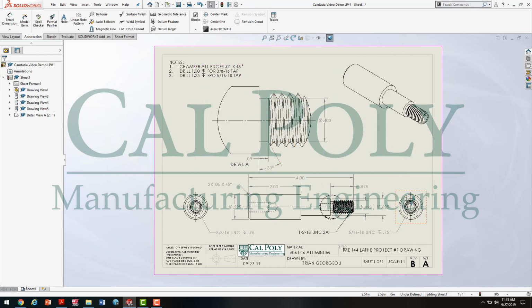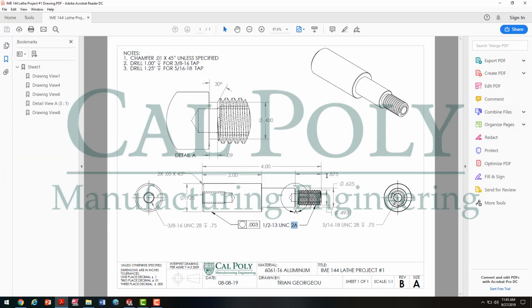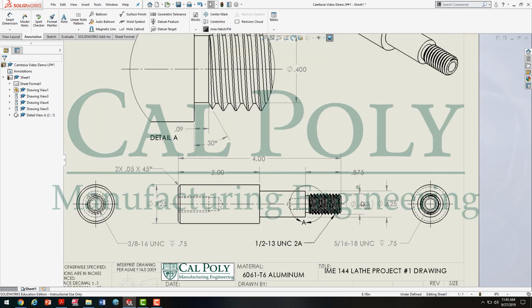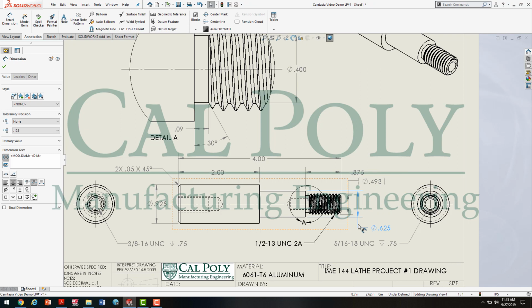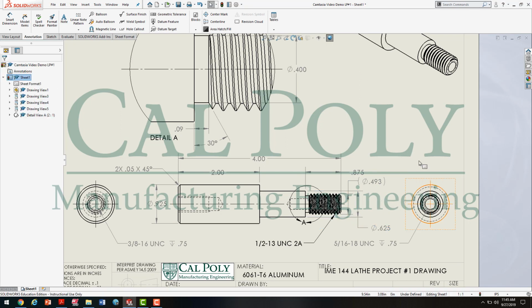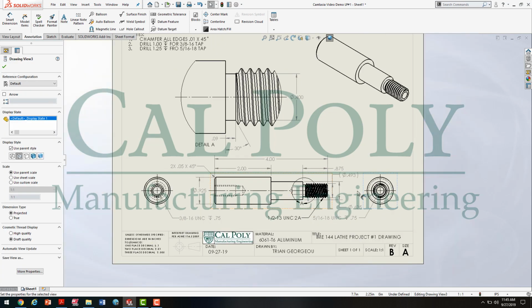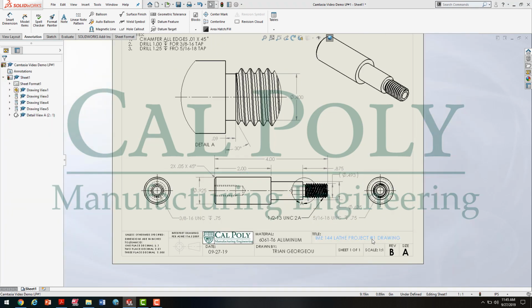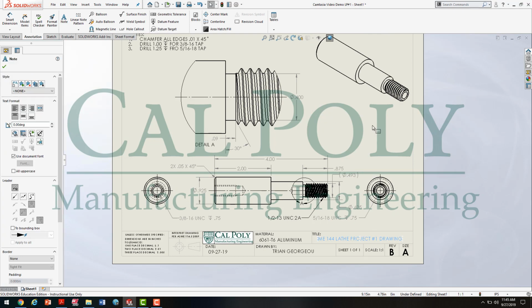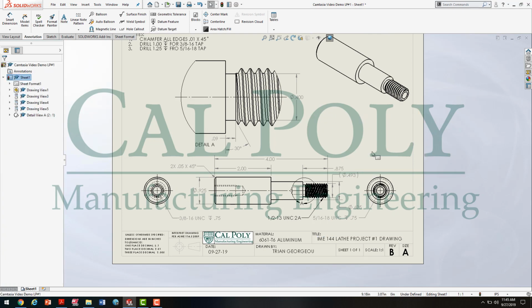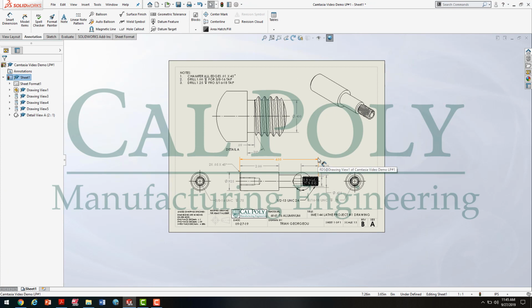At this point, I think we've created everything on the engineering drawing like you see on the one given to you. Now if you wanted to go ahead and clean up the dimensions so they look exactly like this one, we can move back to SolidWorks and realize if I was to drag up and off like this, I can change the way that it shows the actual dimensions, which gives me a little bit more room on my part there. However, as long as they are specified within the ANSI or ASME Y14.5 standards, you're all good. And I've showed you multiple ways to do that.